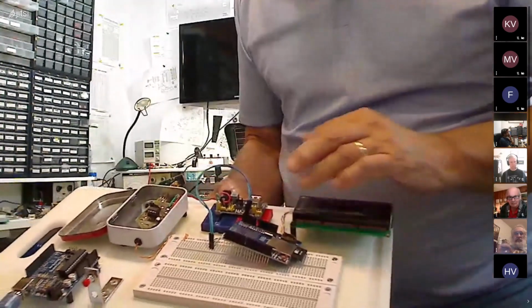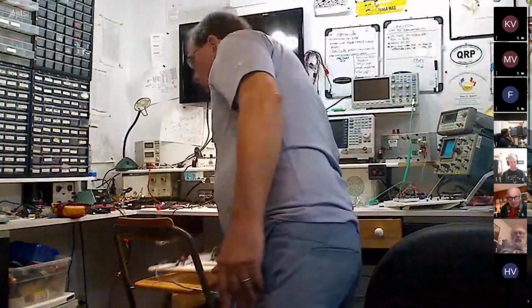Anyway, I went out and I put this in during the rainstorm, and I used a signal generator. And I just put 23 dBm, I think it was, on the antenna. Ran out when it wasn't quite raining so hard, and made a measurement. Then I came back in and took the signal generator away and went back out again to see if it made a difference. And I was within 1 dB of that. So I was quite pleased about that. It was a good start.